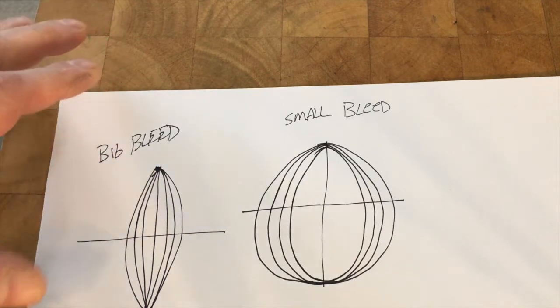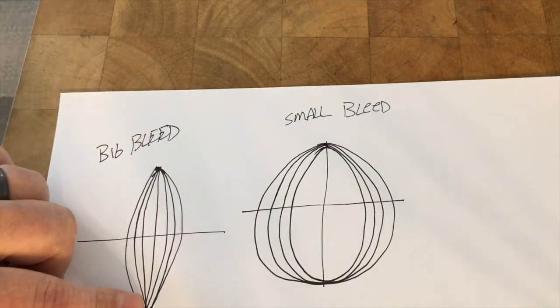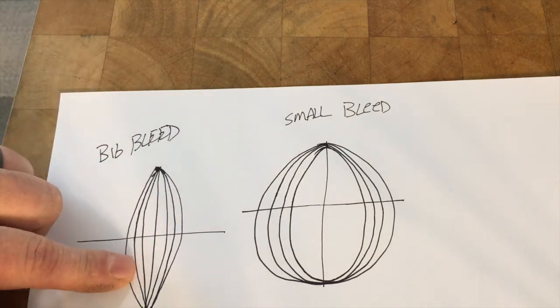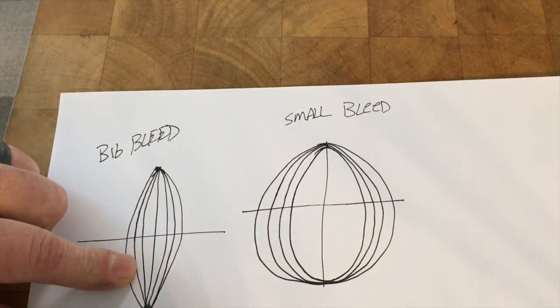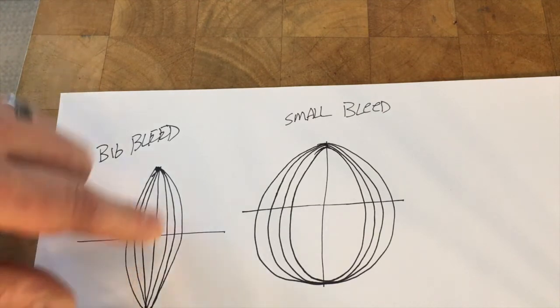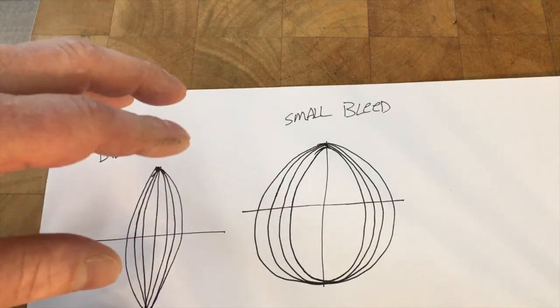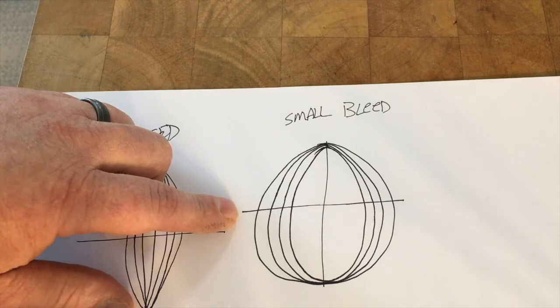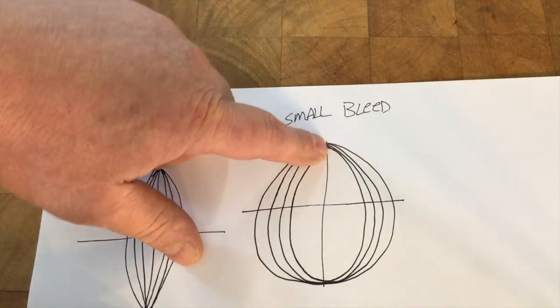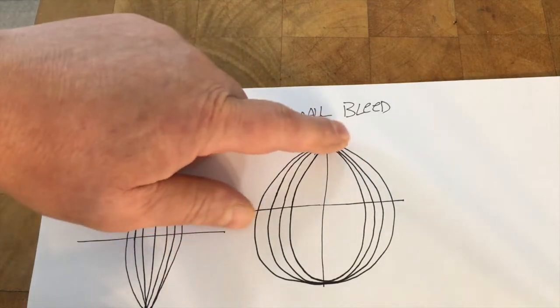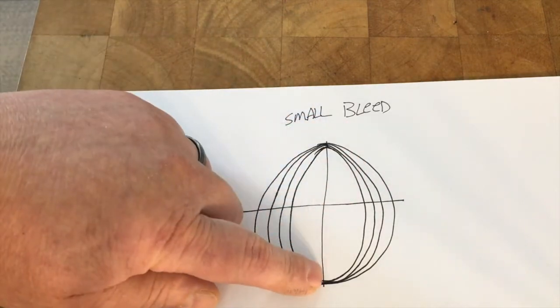It's not entirely the story, but when the flow can go through the piston real easily, it will actually, right here, get like 0 pressure real fast. A small bleed shock with a small bleed plate or a small orifice or whatever it is, won't allow the oil to pass through the piston at the top and the bottom of the cycle.